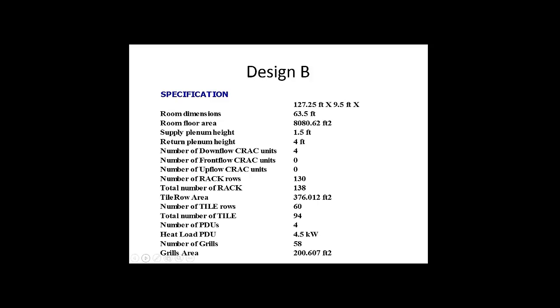So let's look at another design. This one's a little bigger. This is an 8,000 square foot room. It's a raised floor data center, downflow in this case. Return plenum height, 4 feet. And this information comes right from the pre-simulation report that is part of CoolSim. I just dumped it into Excel and put it here.